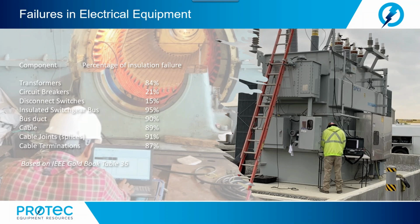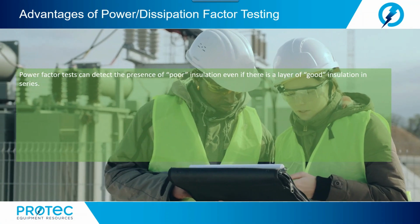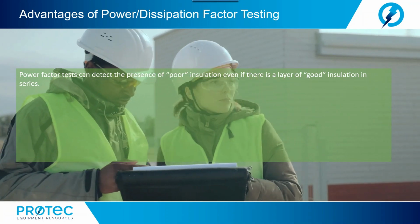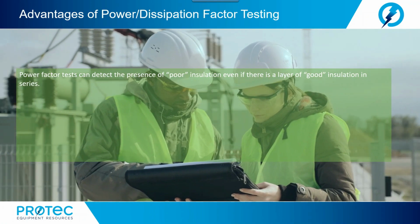The result is a significant decrease in maintenance costs and downtime. Power factor testing is one of the best testing techniques for predictive and preventative maintenance. Power factor tests can detect the presence of poor insulation, even if there is a layer of good insulation in series. However, DC tests usually show a high insulation resistance under this condition.